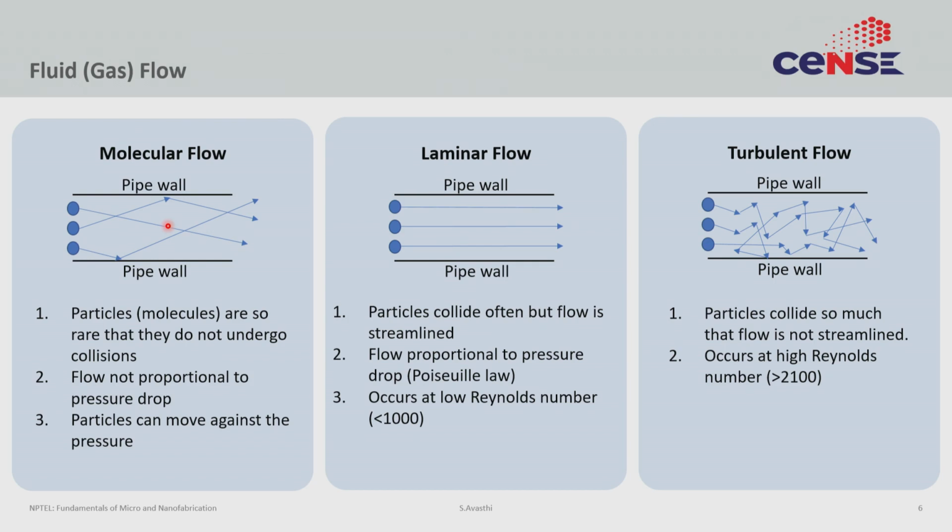So, that can be a pipe, a wall, a chamber, etc. In these cases, the flow is actually not proportional to the pressure drop across this pipe. Simply because if you have a pressure gradient does not necessarily mean the flow will scale with that pressure. This is the case that happens in vacuum chambers. Right? So, if you have a vacuum chamber and very low pressure, then you are in a molecular flow regime.